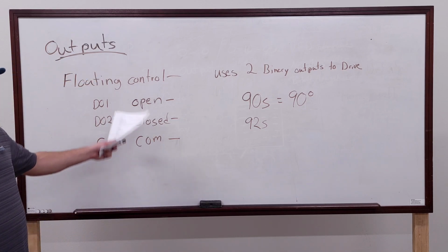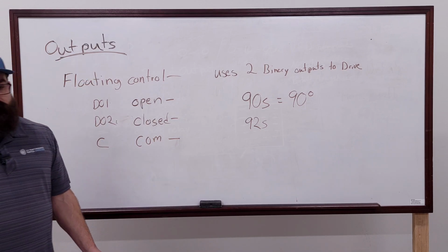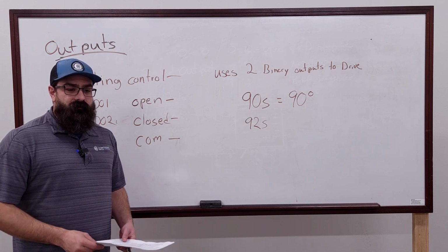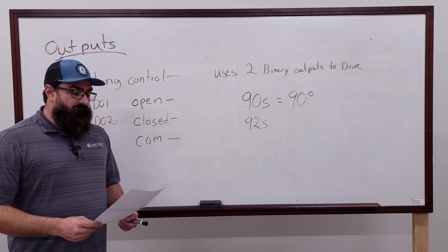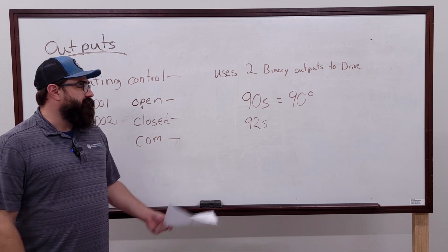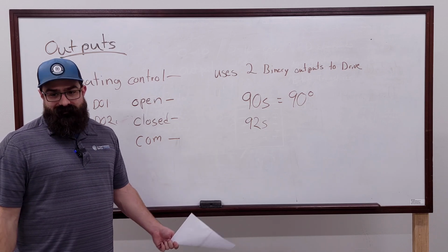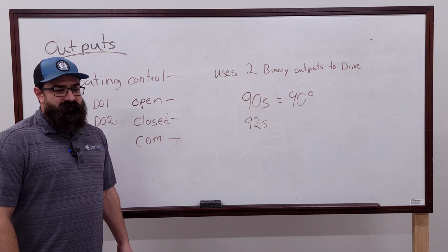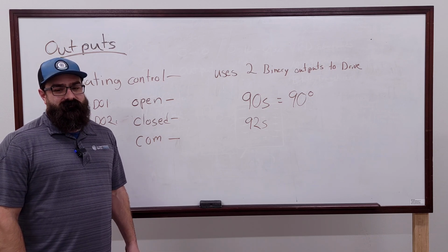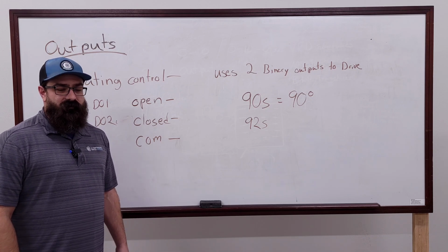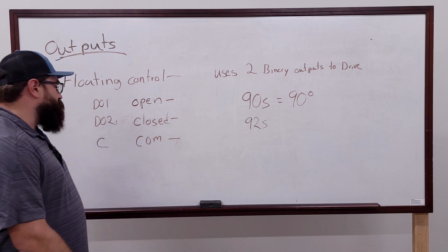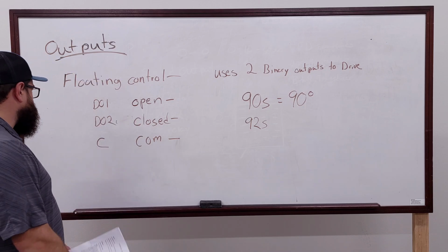It's just because these get out of sync, so you have to put a sync protocol in your controller to make sure they don't get out of sync. So if you don't have a sync protocol, then they get out of whack and you have to manually sync them, which means you force it open multiple times and make sure it opens, and then you force it closed multiple times and make sure it closes. Try and get it back in its range.